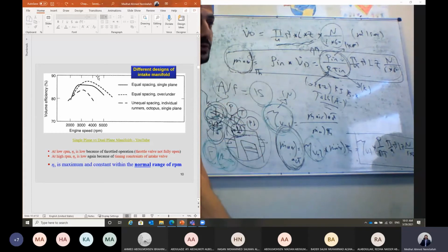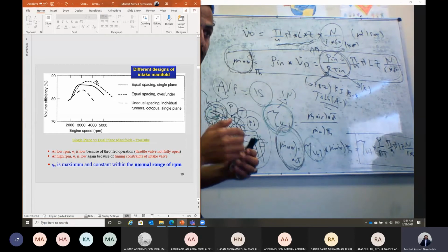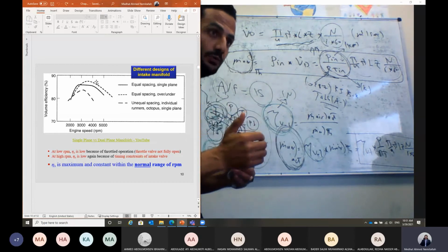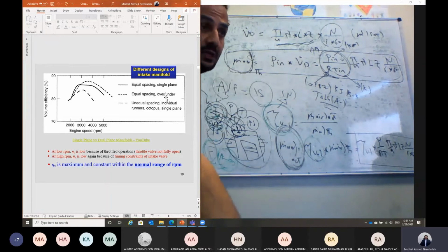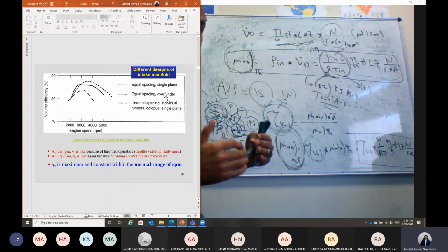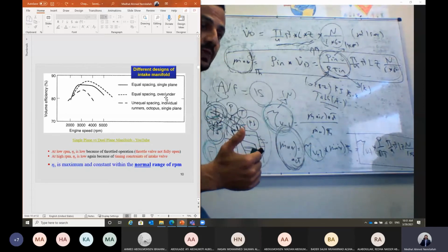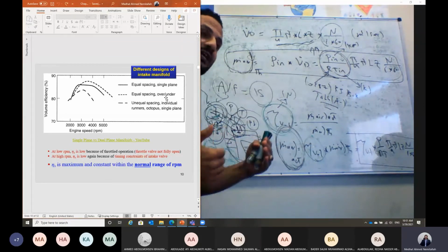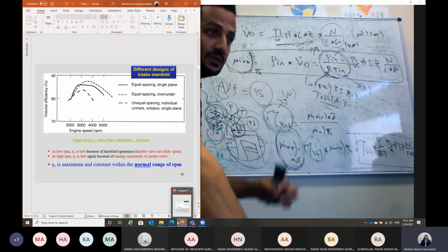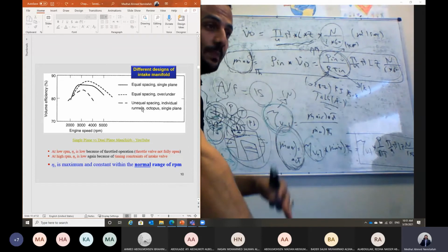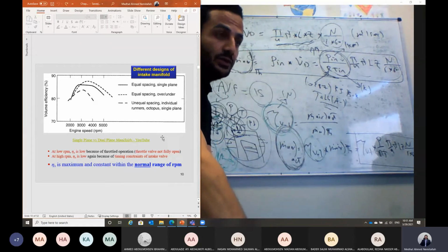And this, Shabab, can be used in the race car. When I need the car to speed up in a shorter time, and I need more air at higher RPM, then in this case I can use what's called the dual intake manifold. A separate intake manifold for each group of cylinders can provide more air to the engine, and it can also respond fast. It has a higher response rate. That's why it can be used with the racing car when we need higher engine RPM.